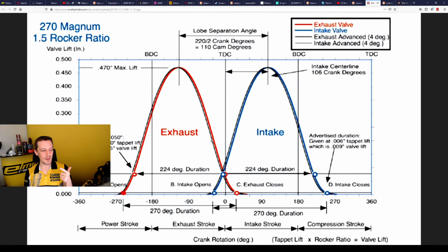But otherwise, to be honest, it's not really that big of a gain, because there are currently technologies like variable cam timing, where you time the camshaft variably in relation to the crankshaft. So you can move the intake and exhaust lobes sideways, overlap more or less, or move both in a direction. That's very beneficial.